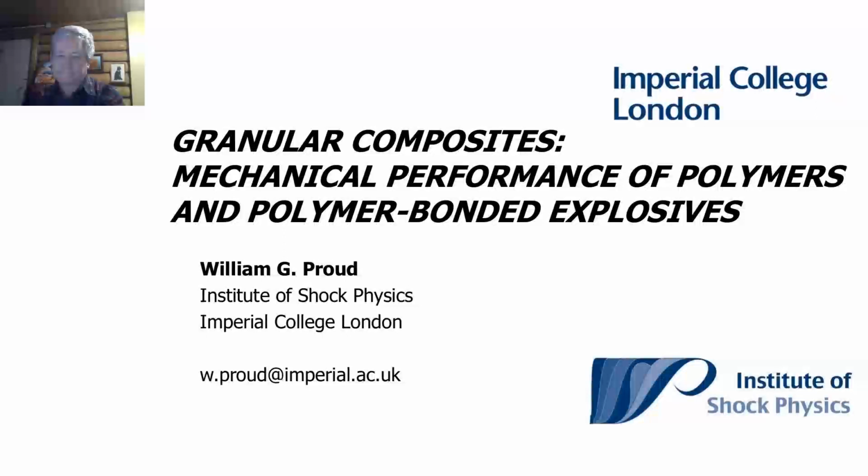Because there are these two, filler and binder, involved, one of them, the binder, will have a marked effect on the mechanical properties if there is sufficient time to manifest those effects. But when you go to shock waves, there's so little time available to manifest that presence and effect that you just get a volume-based response. If you see where I'm coming from, it's temperature and strain rate together, and when you go to very high strain rates, you ultimately end up with a volume dependency.